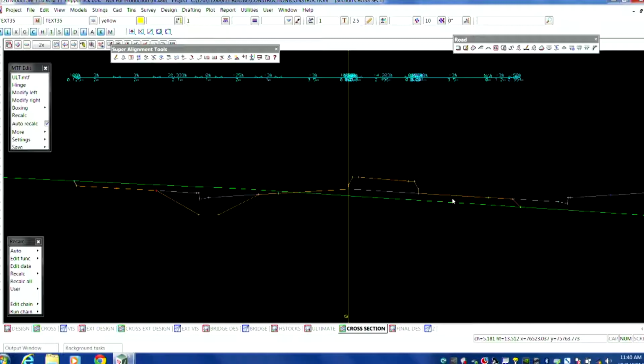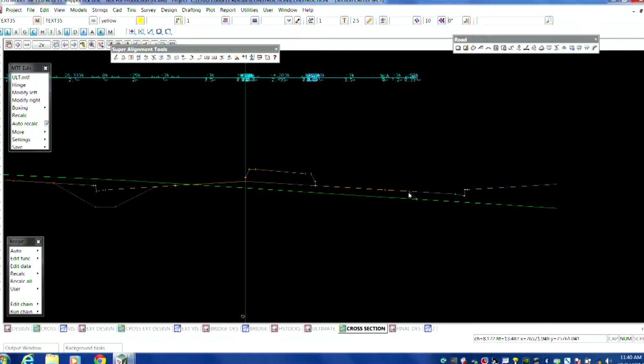So when I come back later on and I decide to put that right turn lane in, it all works. All the grades are all perfect. And I then don't want to build the rest of this part out here. All I want to do is just a shoulder and do a final fill batter. So that's quite a bit of effort to be able to combine all this together. Now we can do all that in one modifier. And the reason we can, one MTF file.